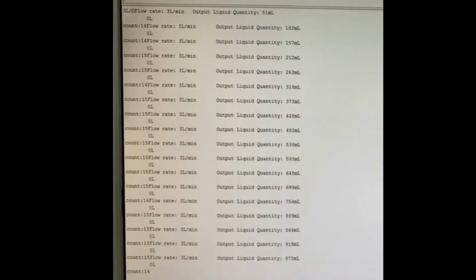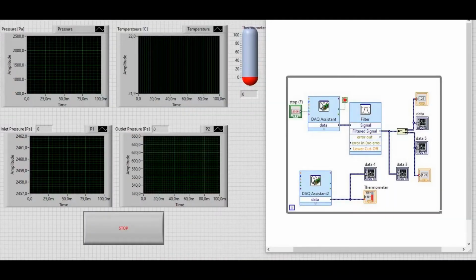The code block running on the Arduino board prints out the flow rate in liters per minute and cumulative total in milliliters every second. So, it is also possible to use the difference between the cumulative totals to get the value of flow rate. Since we have 2 pressure transducers, 2 ports on the NI 9203 module have been used.